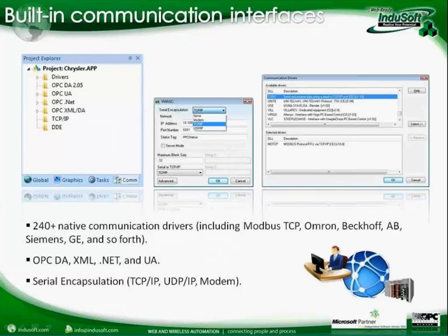In addition to the native drivers, InduSoft Web Studio also has a complete set of OPC client interfaces. So we have been working with the OPC Foundation since 1998. InduSoft is one of the early members and adopters of the OPC interface. We do not force the customers to use OPC. OPC is an option in the product, but should you need to use OPC or want it for a given architecture, it's fully supported in the product. Not only the classic OPC-DA, but also OPC XML, .NET, and UA. InduSoft was even the first HMI SCADA to release a fully functional OPC .NET and OPC UA client on the market.